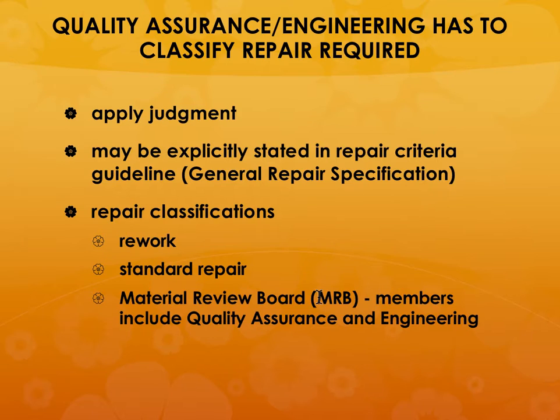There are repair classifications, whether you need to rework the material or whether you can use standard repair. If the damage is pretty severe, then the materials review board has to get together, with members from quality assurance and engineering, and make a determination whether this component can continue to be used, or needs to be repaired, or whether it needs to be scrapped.